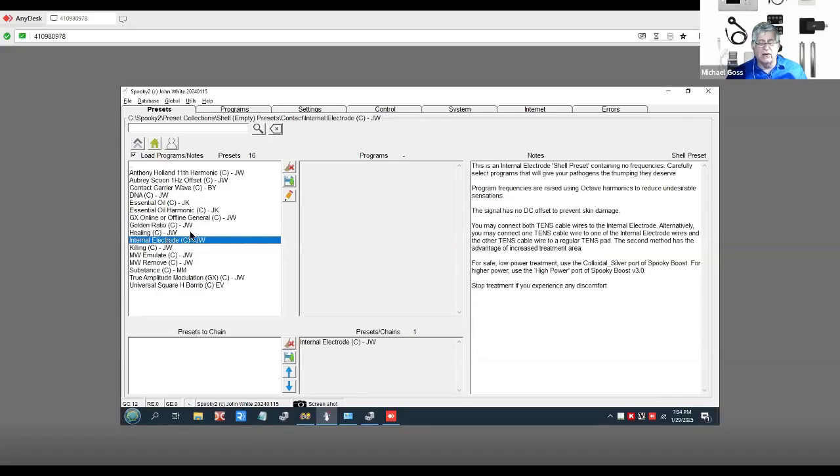And just as a side for contact mode, for those of you who have a GX, so you can do it in offline mode without a computer, one of the caveats of that is it's not smart enough to reduce the amplitude. So if you're running 400 hertz or whatever, you're going to feel that, because if you have the computer controlling it, the computer can reduce the amplitude so you can't feel it as much.